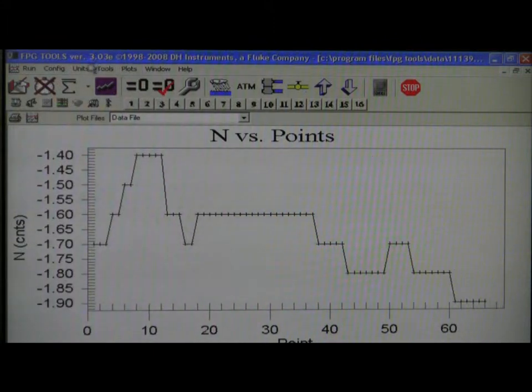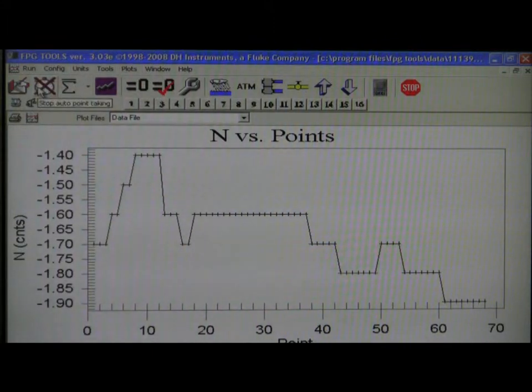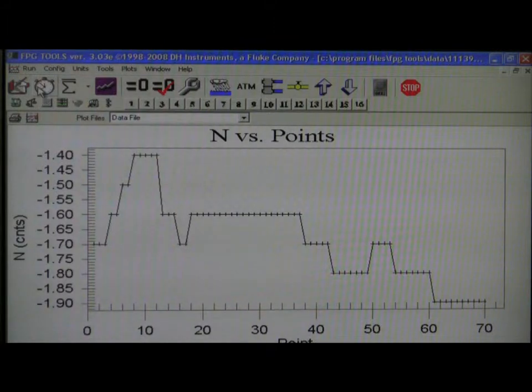So at the end of 60 seconds, we go up to the stopwatch and we press it again to stop the point logging. And now becomes the time where we analyze the data. On our screen, we're first and foremost looking for a section where there's no change for 10 seconds or more. This section right here begins at about 19 seconds and continues unchanged outward to about 37, maybe 38 seconds in time. Our criteria is 10 seconds or more, zero change, and we definitely have that met here.